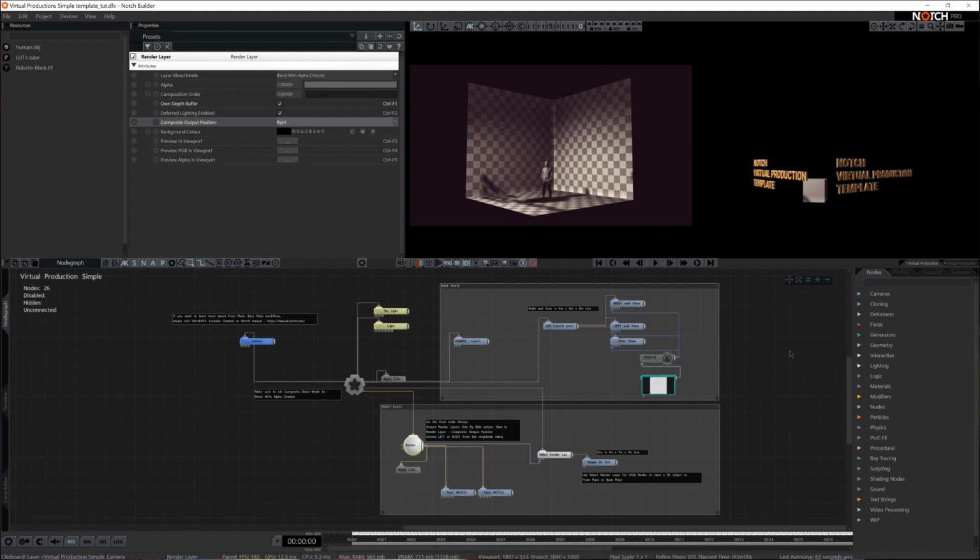In this example, we have backplate and front plate set up to render side by side in full double HD width in the viewport. This is done just so we can see better what is happening. When we are working on our designs, we don't need to double up our resolution in width for it to be read correctly by media server. Bespoke media server will do this calculation automatically internally, so you can keep your original scene settings at all times.